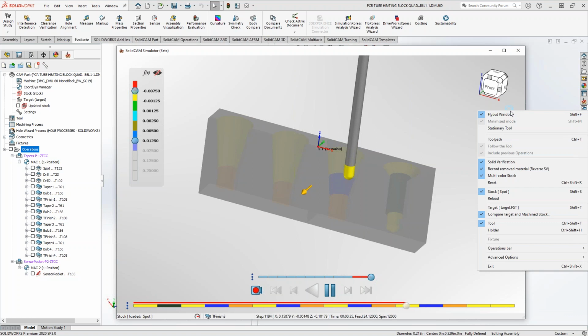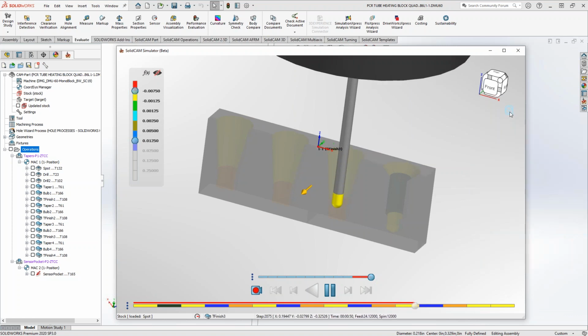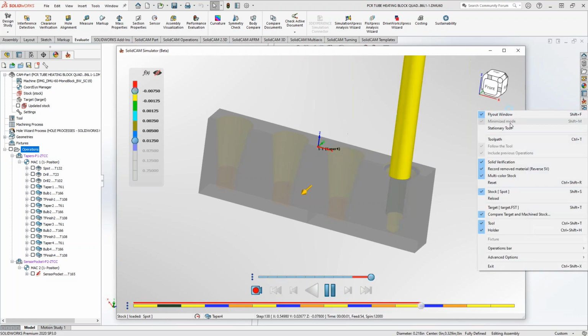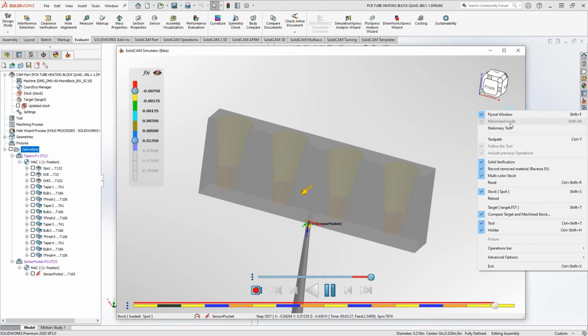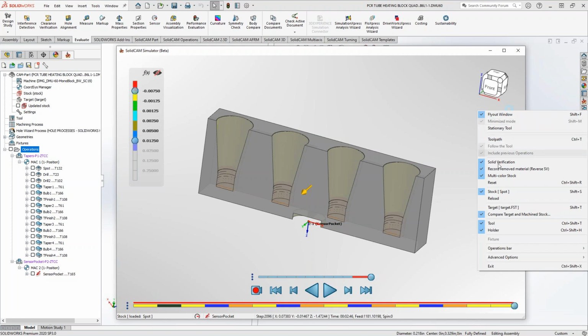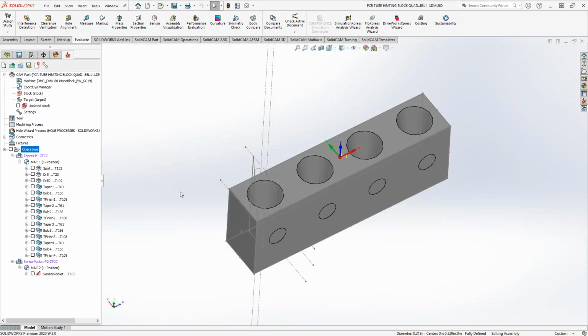So if you have a 15 thou tolerance in there and it's showing gouging, we want to be as accurate as possible. If you're looking for a really precision fit, I would definitely recommend changing those settings to a lower number versus a higher number. And maybe, just for review for everyone, let's go ahead and show that in the Solid Verify settings.